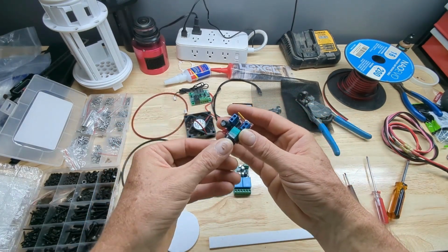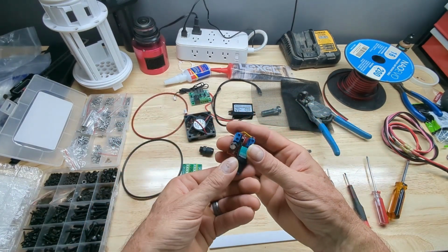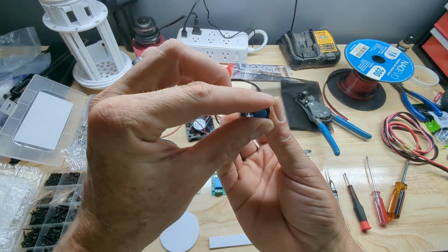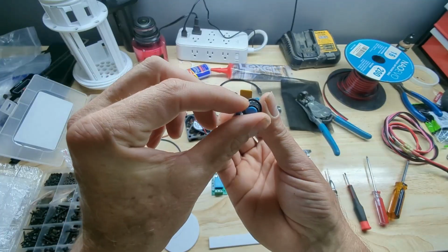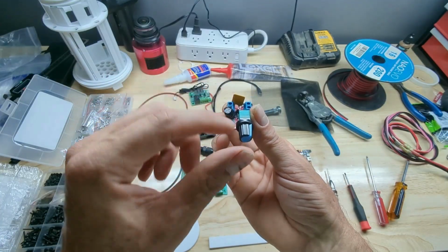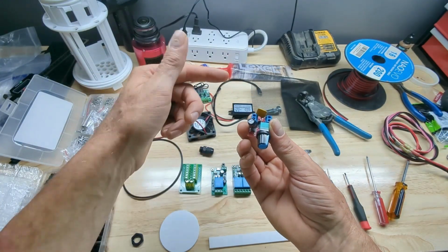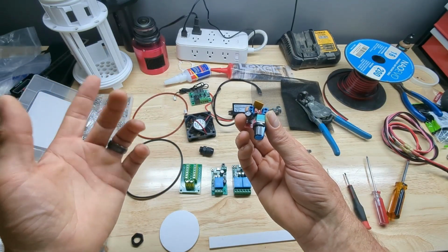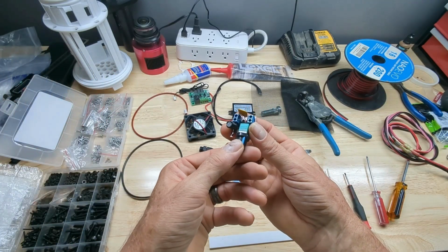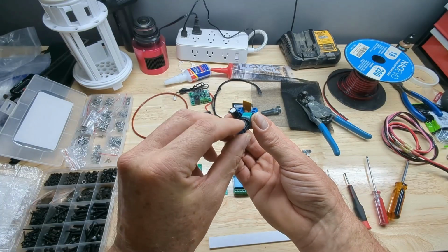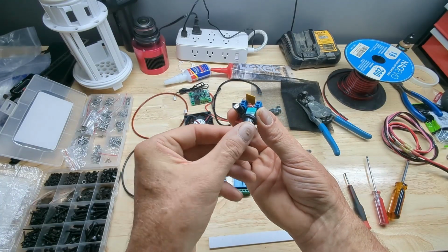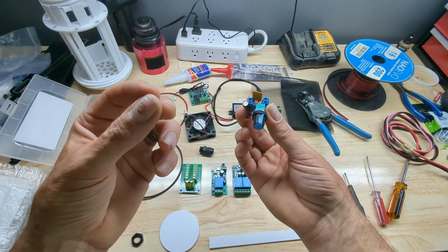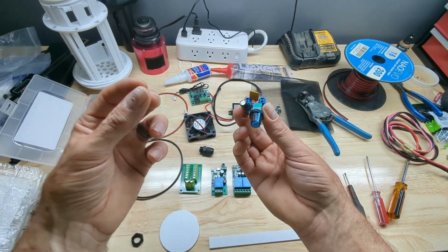This is a PWM controller. This is what we control the output of our dew heater with. So you'll hear it maybe click, that when you turn it, say about halfway up, that's going to send half of your 12-volt power to your dew ring. Whether you did a DIY dew ring or you bought one from the dew control people, it's good to have one of these because you don't usually ever need 100% power to your dew ring. Normally about 50% is sufficient. You're just trying to heat the dome up just above the temperature on the outside to keep dew from forming.